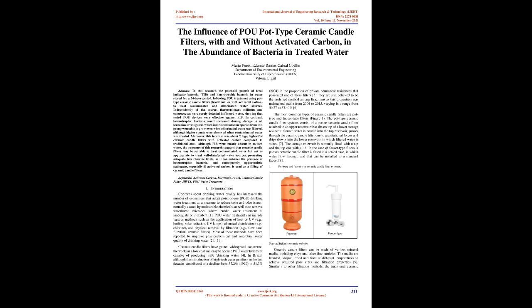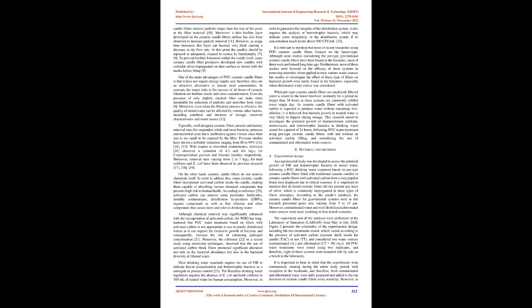Moreover, even when the filtration process is effective, the quality of stored water can be affected by various other factors, including condition and duration of storage, reservoir characteristics and water source. Typically, well-designed ceramic filters present satisfactory removal rates for suspended solids and most bacteria, protozoa and microbial cysts, but are ineffective against viruses since their size is too small to be retained by the filter.